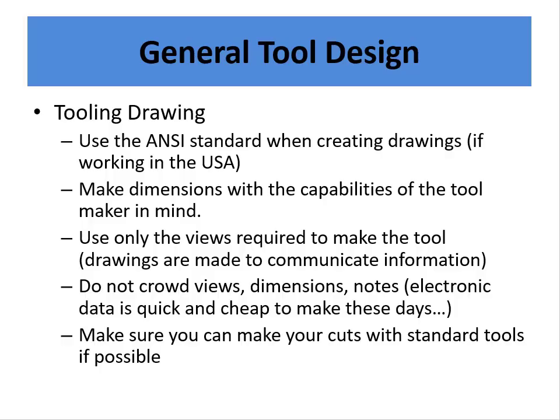You don't want to get there the first day and put some ridiculously tight tolerance, or something that's not normal, on the print, because then it's probably going to tip people off that you don't really understand what's going on here. So you need to understand the lay of the land, so to speak, for that.